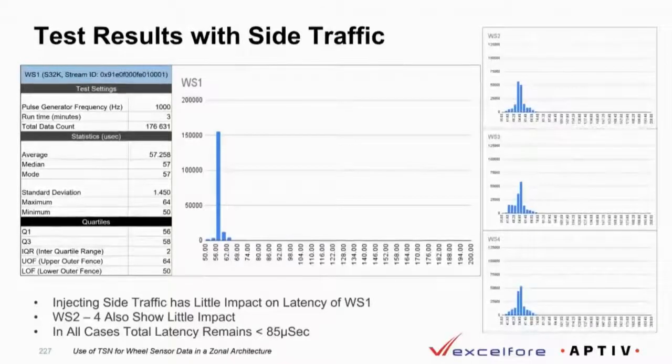If you use the credit-based shaper, first of all, the sample signal is short. Even if you are having the payload go into the credit-based shaper, you're getting the gaps, and then the signal is passing through. And the total latency is still 85 microseconds. So in this case, you can see that all the real signals and the synthetic signals are all within a certain range for you.